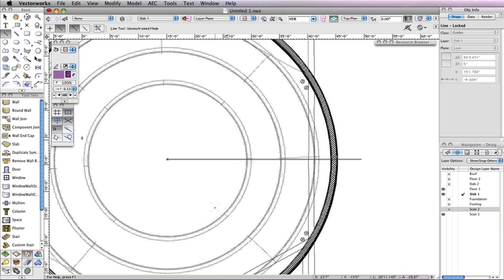The gray highlighting means your selected object is locked, which you can also see in the Object Info palette. Also in the Object Info palette, notice the Lines class has changed from the None class to the Guides class, which is automatically created the first time the Make Guide command is used.